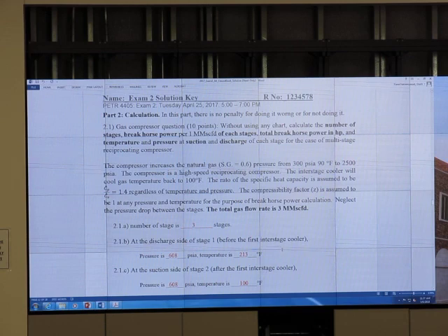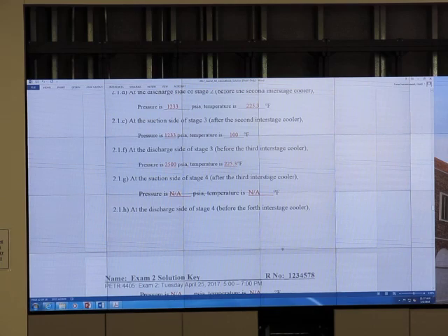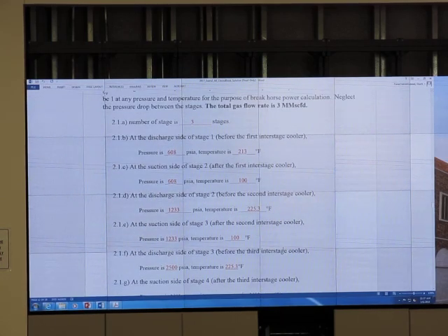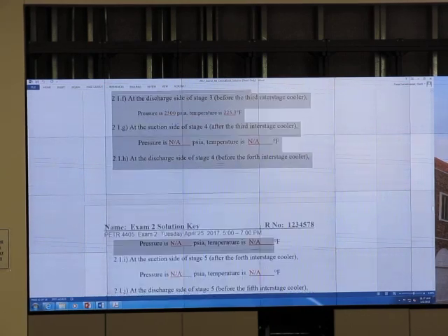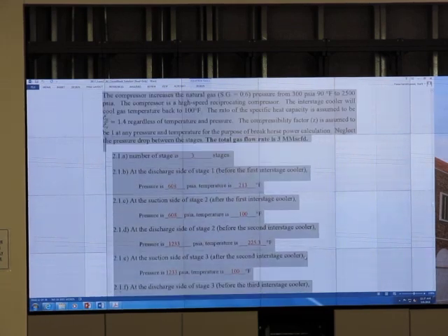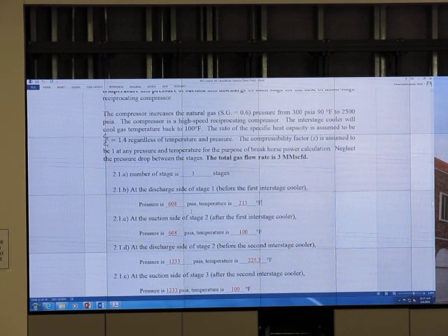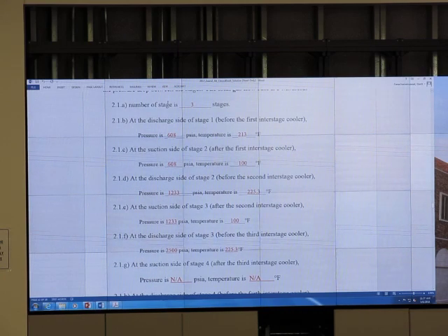Is it fair to put this into our exam, Rohan? Yes, it is. It is very fair to put this question into my exam because it is about discharge pressure, discharge temperature. This is just one equation, right? Number of stages. The compression ratio between each stage should be between 3 to 4. Just use 4, okay? I think in the exam maybe you cannot go more than some value, okay? And the exam will tell, and you should be able to tell, how many stages, what is discharge temperature, discharge pressure.